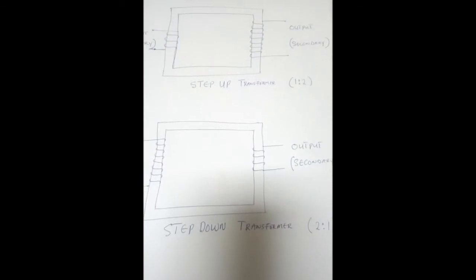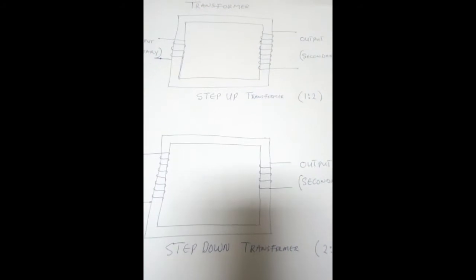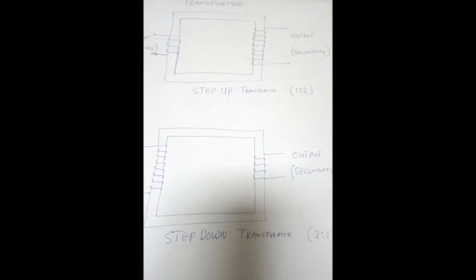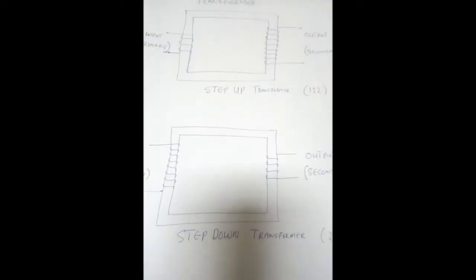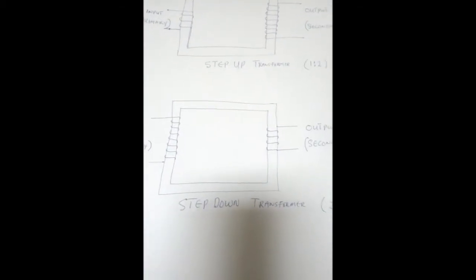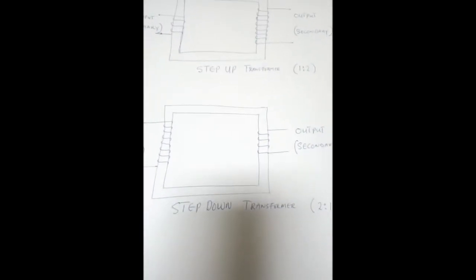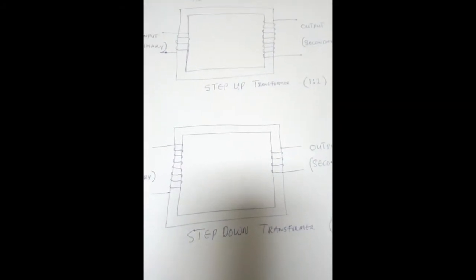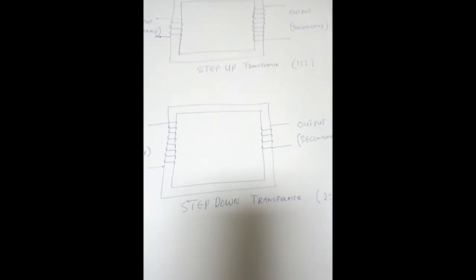But if you really want to use a 50 Hz input for a 60 Hz transformer, there are things you can do, maybe like lower the input voltage or add more turns to the primary winding. But it is important that you understand that if you just apply a 50 Hz input to a 60 Hz transformer, it is going to generate heat as a result. So be careful and watch out, whenever you're changing a transformer, whether it is a 50 Hz transformer or a 60 Hz transformer.